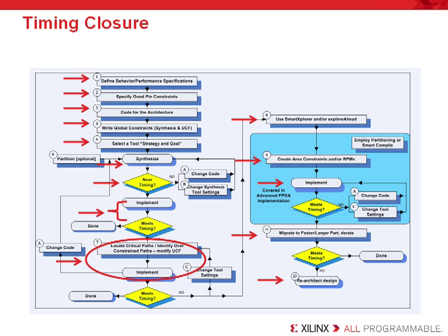Finally, before synthesizing, it's recommended that you choose a design strategy and goal. This is an automatic way to guide the implementation and your synthesis tool, that is XST. This will enable algorithms and software operations that will help you meet your objectives. So it's a very simple way. Not all of our customers use it. For some customers, it's very high level. They'd rather get in there and customize the options for synthesis and place and route on their own. But it's up to the user.